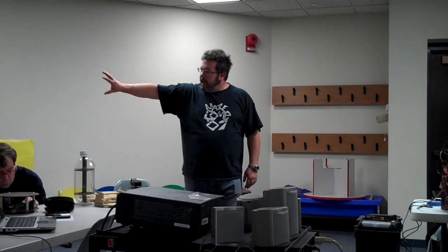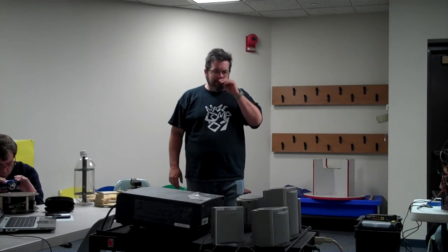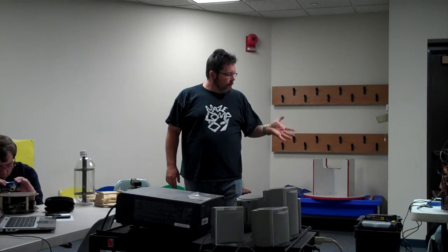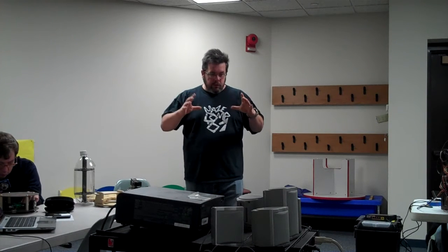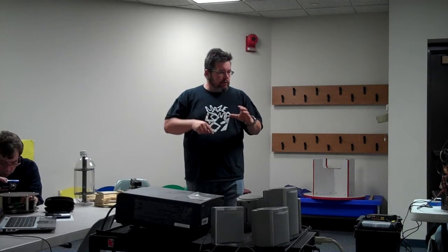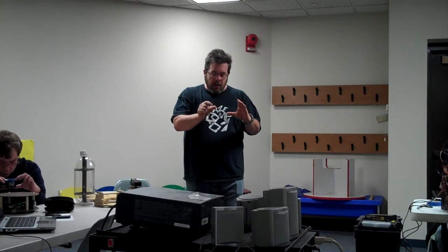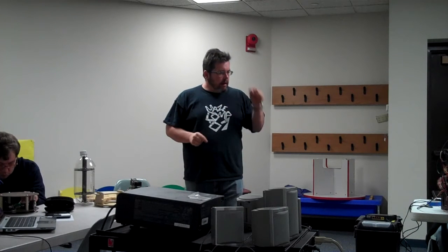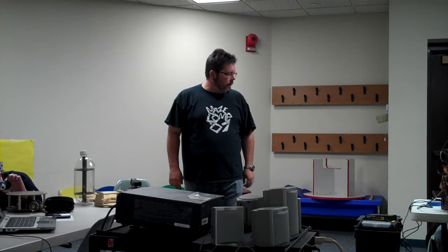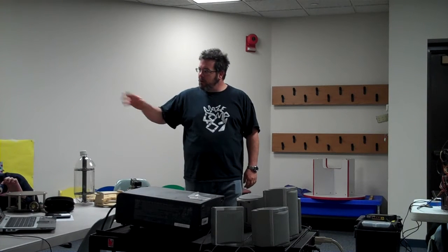So once that's drawn up in the CAD, it gets exported as a DXF, right? We're all familiar with that. It's a drawing exchange format, or it stands for something. Anyway, it's a standardized format that the CAM program will then use. Then I'll define all my tool paths. I'll say maybe for this cut, we're going to use a tool that's 1/4 inch wide, and for this cut, we're going to use one that's 1/8 of an inch wide, and go this deep and go this fast. I tell it the speeds and the depths and all that kind of stuff. So we're going to see that in the CAM program.